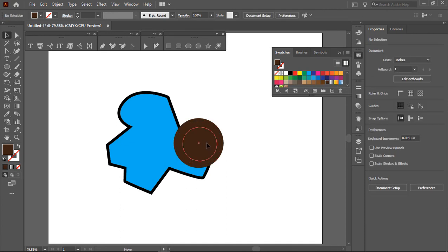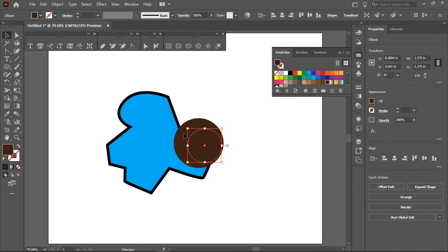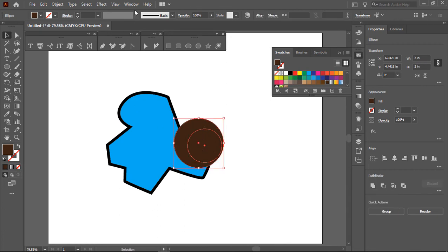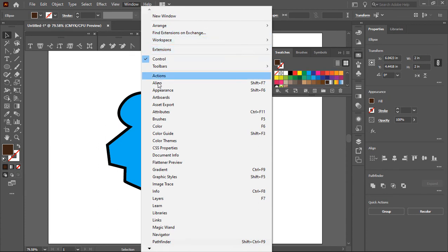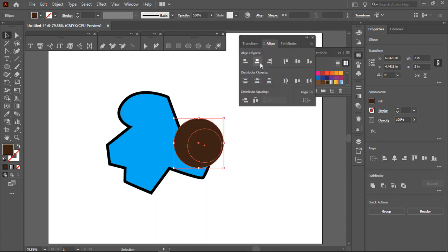Okay. Now, if you notice, these two are overlapped. If you can't see them, do a Control Y. Okay, now you can see them. I'm going to select this one here too. Hold my Shift key down. Now I got these two selected. I can come up here to the right where it says Align, or I can come over here to my Align pop up here. And what I'm going to do is align them by center. I'm going to align them by middle. That's pretty cool.